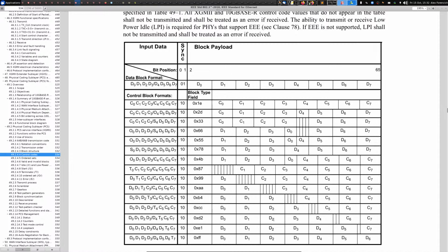The other thing that this provides is the ability to send some small amount of out-of-band data, right? There is a split between the data symbols and the control symbols that you can send down the link. And this is extremely useful because you can use a small amount of control information to indicate, unambiguously, the beginning and end of frames that are sent down the link. For something like a UART, there isn't really a nice way of doing that because the protocol doesn't really support sending out-of-band data. There's a couple of techniques that I've heard about.